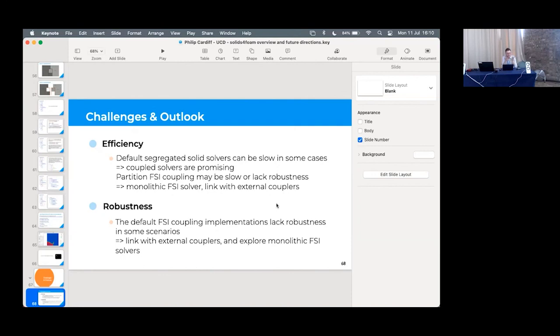So for multiphase, like if you've interFoam, then they're independent because it's partitioned. It's just an interFoam case and a solid case. So any boundary condition you can use in interFoam, you can use in, like, the fluid model in Solids4Foam. I'm not so familiar with them, but there's like a constant angle one and something else. So you can use all of those. And the only thing you need is the force. So the interface just needs the force, which is just like pressure plus viscous stress or whatever. So the alpha equation doesn't really matter.